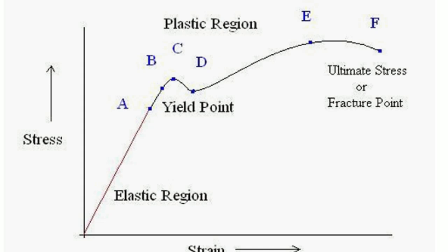Now, what is happening if we increase load further? Then the material shows a curve from D to E like this. So what is this portion D to E? After yielding has taken place at D, further straining takes place in this portion by increasing the stress, and the stress-strain curve continues to rise up to the point E. The strain in this portion is about 100 times that of the portion O to A. So from this point to this point is 100 times, and the point E is termed the ultimate stress point or ultimate tensile stress point.